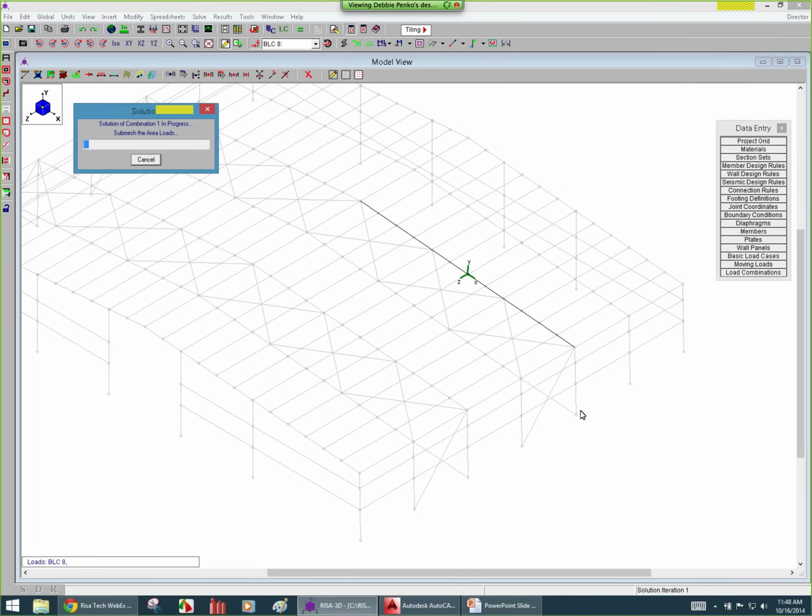So that should, as we run the load combinations, really change some of the reactions, and we'll see more of the design. Analysis didn't change in any way, but what did change is that the code is now going to change its unbraced length instead of using the full distance. By default, it's conservative for the program to say, I don't know what's going on with the construction of this, so we're using the full length of the member. And then it's the engineer's discretion to say, well, actually, this is bracing this.